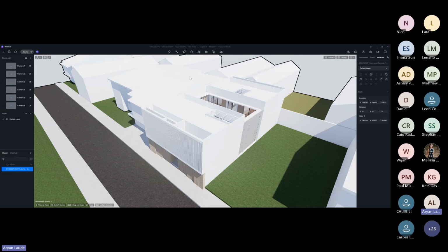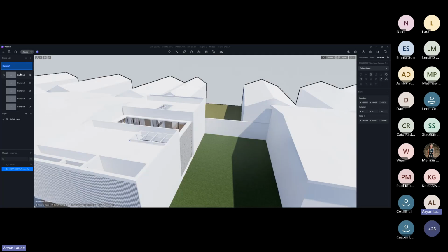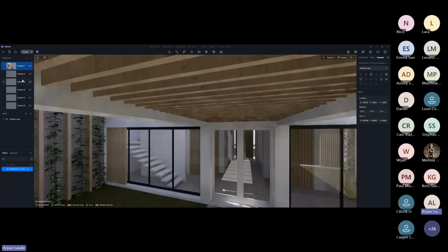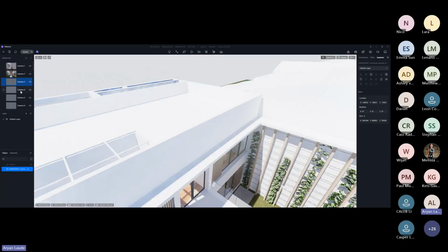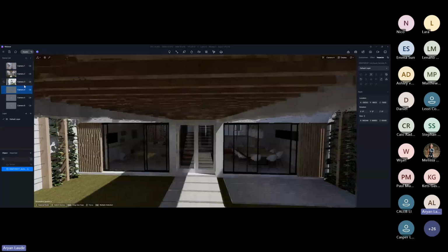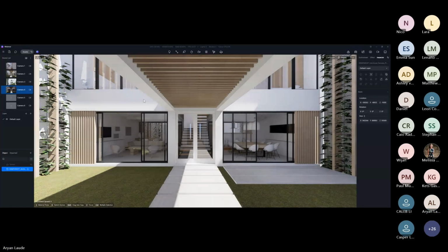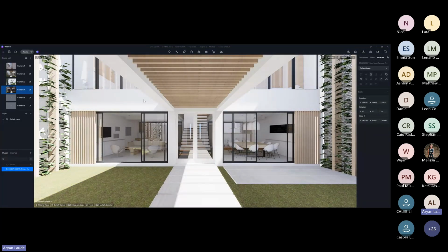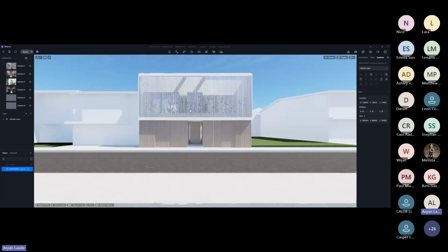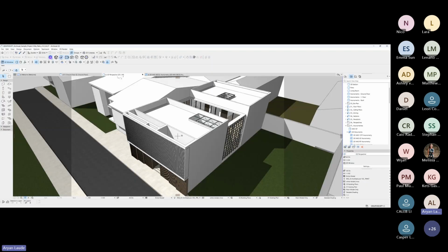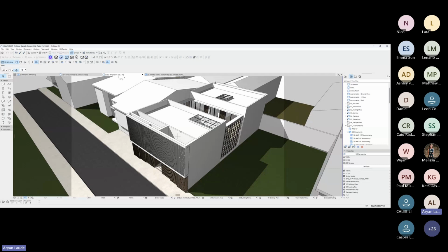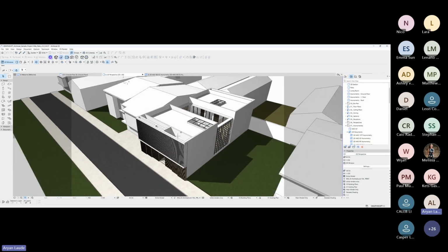And I can now just focus my whole screen to D5. I can go back and forth to any camera position that I have added in from my ArchiCAD to D5 render. So this will significantly save you a lot of time going back and forth from your 3D modeling software back to D5 itself. And if I have also done the lighting options inside my ArchiCAD, and I don't want to manually redo this inside D5 render, I can just select the sync light and it will also transfer out the light options inside my ArchiCAD straight back to D5 render.